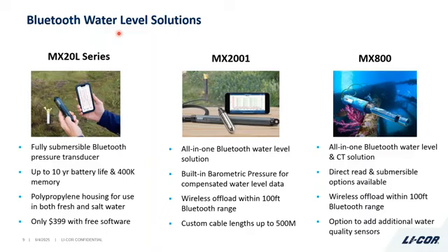And with that Bluetooth built into it, it's true wireless offload. That's one thing that HOBO does unique compared to other options on the market is that we build Bluetooth into these loggers so that it is true wireless offload. You don't need to attach a dongle to it, for example. With that barometric pressure, it's giving you water level data right out the gate. You're punching in your reference level from the very beginning, and you're off and running from there.